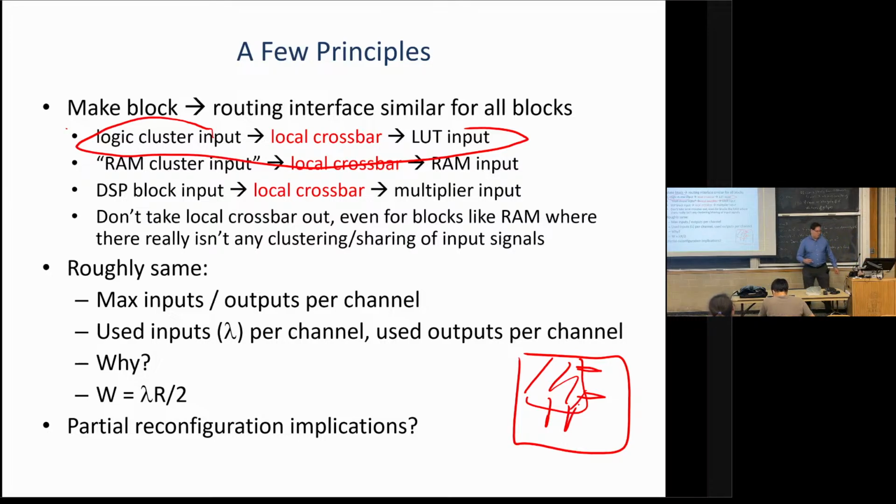When I actually do the routing of the new thing that I want to stick in here, I'm doing that offline, but the router has to succeed. The signals going into it start on wires, not on block outputs. But block outputs can reach a bunch of wires. So just starting on a specific wire is fundamentally harder. And the connections coming out of here don't end at a LUT or a RAM, they end on a wire.